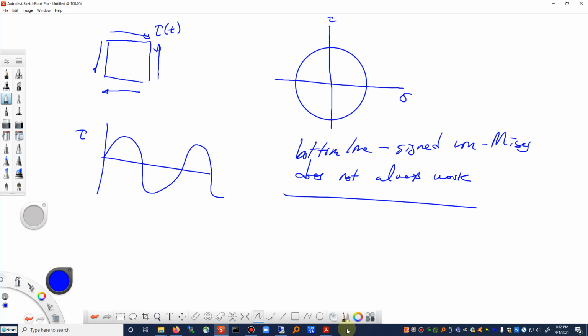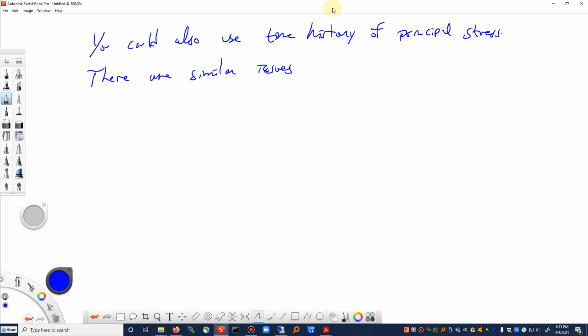So you might say, well, why don't we just use the principal stresses? And you could use principal stresses. You can use the time history of the first principal stress if you'd like. But again, in situations where you have pure shear, you get into this kind of weird issue that we have here. Let me make a new slide for principal stresses. All right, so you could also use time history of principal stresses, and there are similar issues.